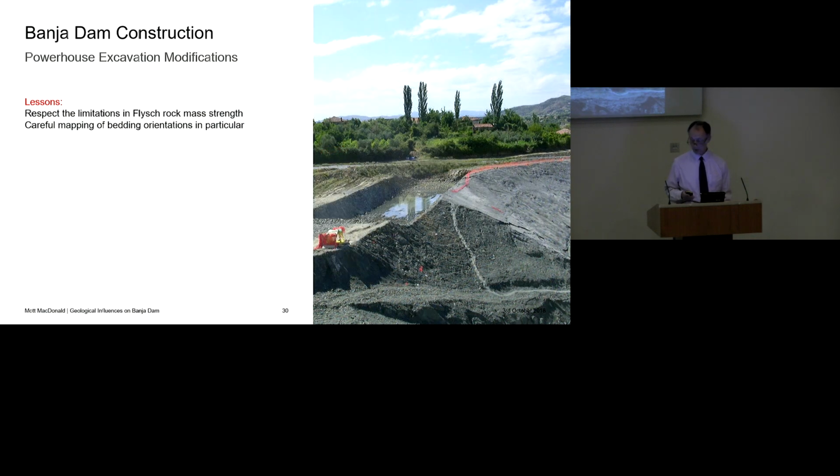As here, you can see the excavation for that stilling basin structure has been pushed back, and even when we did that, you can see that we're still getting very close to a few little failures and some cracking across here and so on. So it was a good lesson to us all, and to us as design reviewers as well, that you couldn't push it too far.